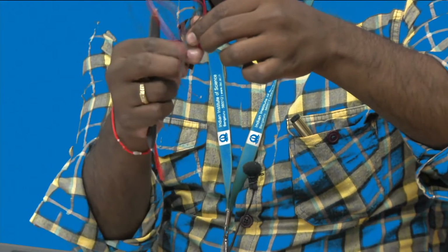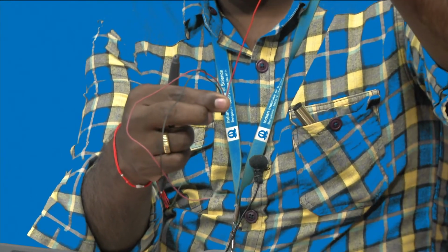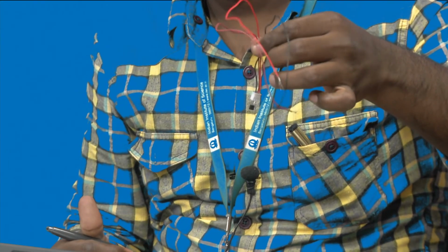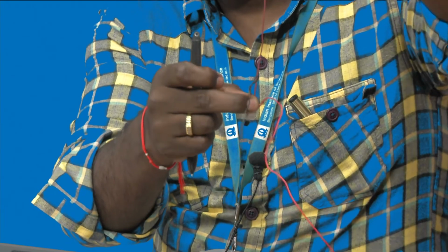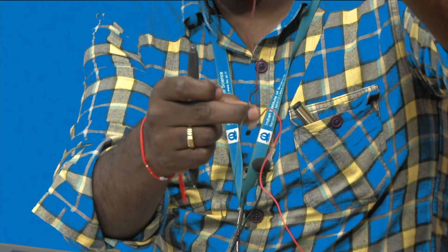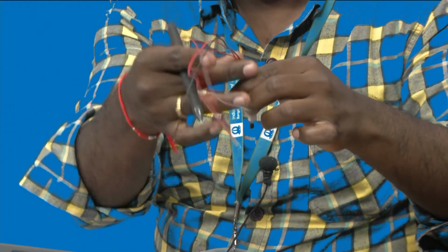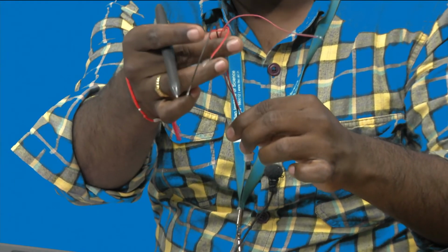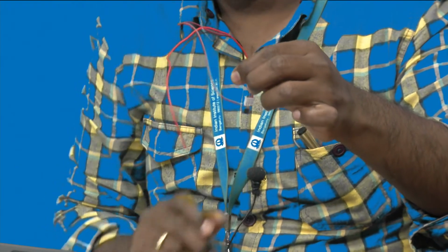Here we can see that this red wire of our RMC cable connects to positive, so a positive voltage which can be applied from 4 to 20 volts. Then the center, which is a brown cable, is V out. Whatever voltage we measure is with respect to the ground, and the ground terminal is a black wire. So we have connected in such a way that connecting these wires to a power source and an oscilloscope or a data acquisition device will directly connect to the LM35 temperature sensor, right. This is what we have seen from the data sheet.